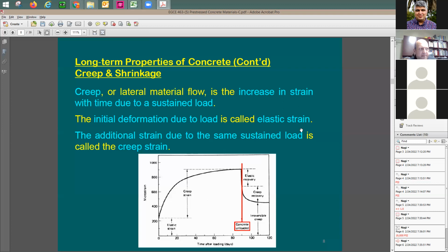If you remember the meaning of creep, for example, if you bring a structural beam, any structural beam, and then you put it on two supports. You put here a point load. Once you put the point load, you can measure the deflection, the amount of sagging that happened in there. Then you say, okay, this is how much the sagging is going to happen. Instantaneous deflection, which means elastic deflection. We call this elastic deflection. You measure it, let's say half an inch. You say, good, all right, half an inch, no problem.